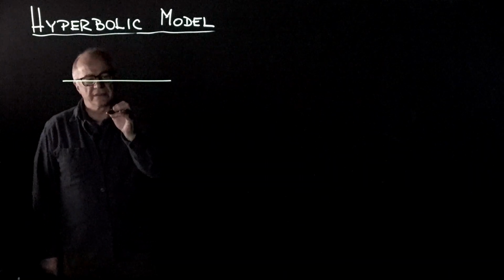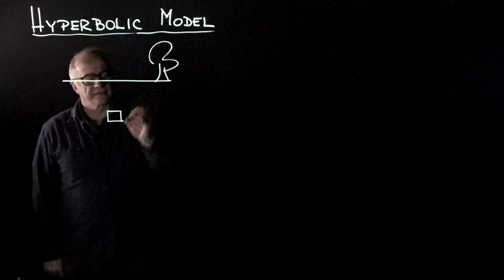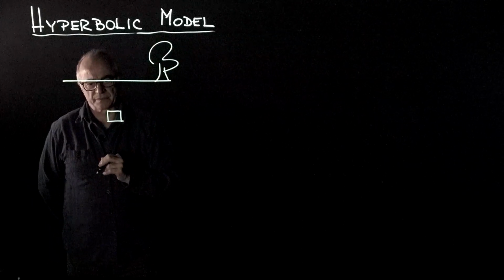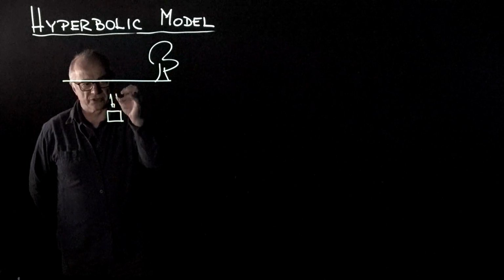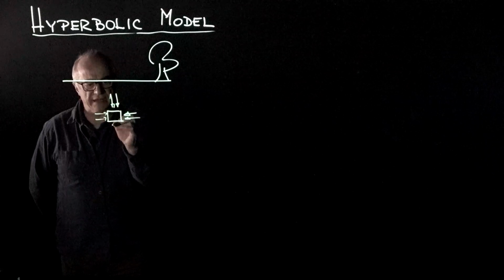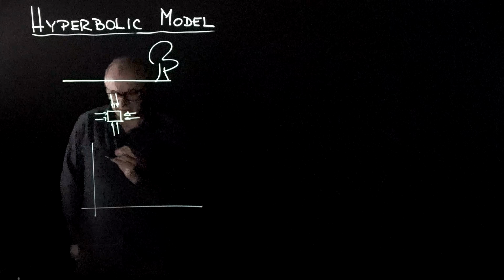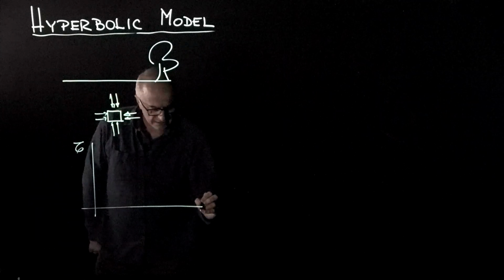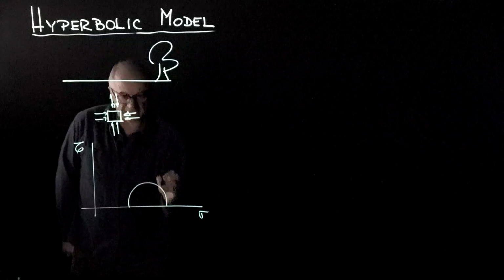A soil experiences a certain state of stress in the subsurface. That state of stress, which is going to have some vertical and some horizontal stresses applied to it, can be captured in the tau sigma space by a Mohr circle that represents the state of stress at the point in equilibrium.